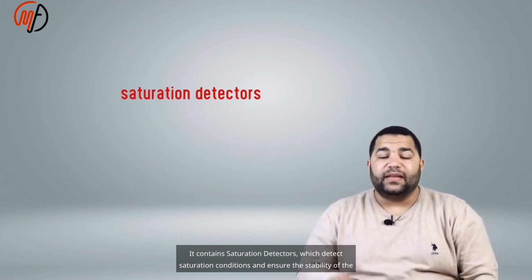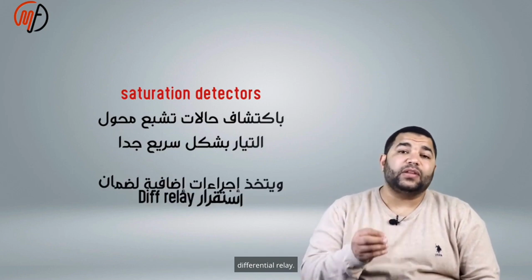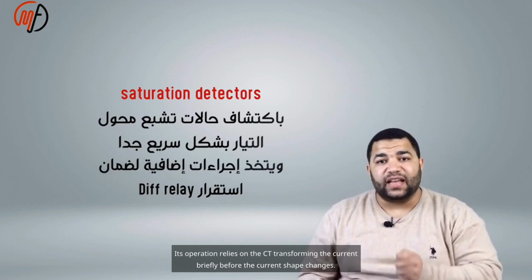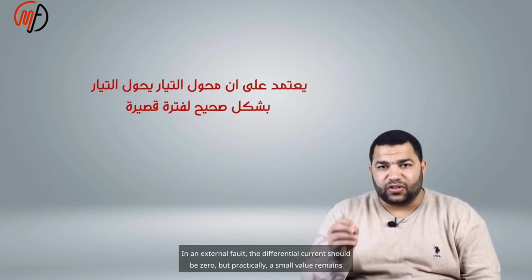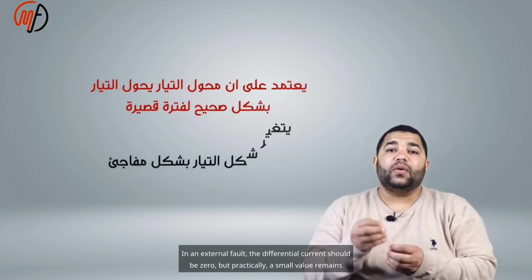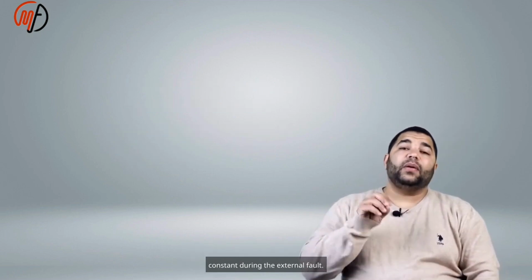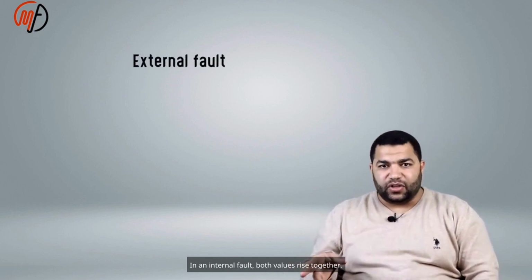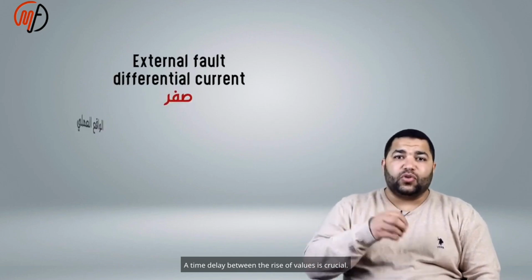It contains saturation detectors, which detect saturation conditions and ensure the stability of the differential relay. Its operation relies on the CT transforming the current briefly before the current shape changes. In an external fault, the differential current should be 0, but practically, a small value remains constant during the external fault. In an internal fault, both values rise together. A time delay between the rise of values is crucial.